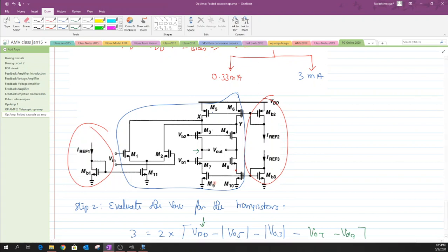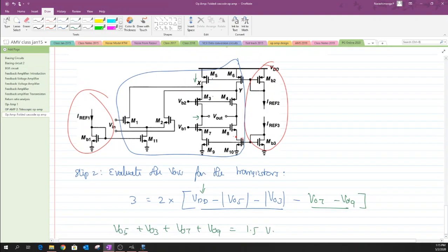circuit conditions. Okay. Now clearly you could see that the transistor M5 carries most of the currents, right? Because as we had discussed, the current flow driven by this entire structure starting from M1 all the way to M11, including all the transistors between them, has to have a total bias current of 3 milliamperes, which means that each of these branches, this is my branch 1 and branch 2, has to support a current of 1.5 milliamperes, right?